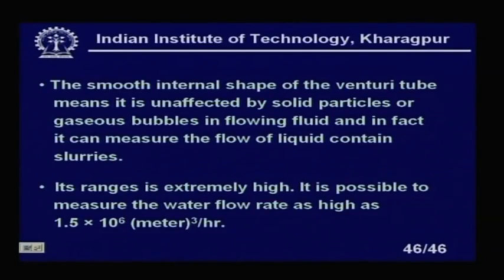The dimensions will be quite big, I agree, but this type of high fluid flow rate, or volumetric flow rate, will never be achieved in any other flow meters. This is very important, right. And please note that this is also needed in some situations, because in those situations you will find that I need a flow meter with a differential pressure output, as well as a flow meter for a large quantity of volume flow rate. In that type of situation I have to use the Venturi flow meters. So, this is very important for measurements, right.